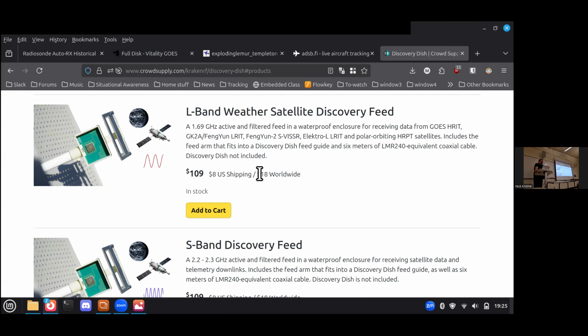What you can also do is get another grid antenna and mount that grid to the back of your existing grid so it makes it even bigger. And then also something you can do is the little metal thing in front, flip it around. Flip around, yeah. I've tried that. We made a custom feed for like 1.7-ish gig.